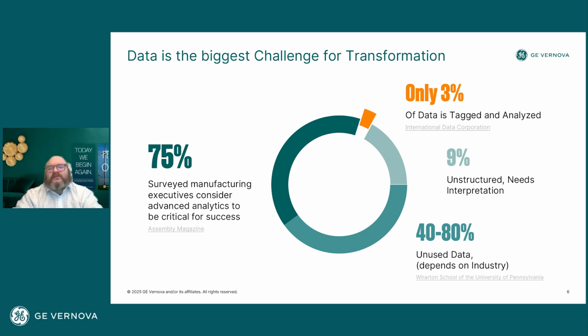Tagged and analyzed. This is really where historian is key to the operation. Tag data, you know where it comes from. You can give it a tag name that gives it a place that you know where it is coming from. What is it telling you? Like what machine are you learning about? And then analyze. Once you have the data in there, you can tag and analyze it. The cool part with Data Hub is once the data is tagged, you can move it into a unified namespace where you'll have the same sort of structure across all of your plants.